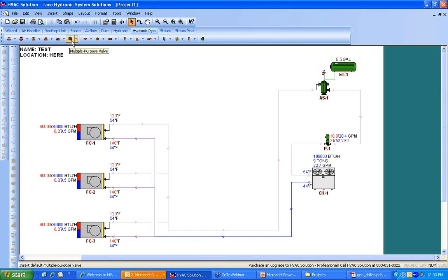You can put as much detail as you want into this drawing, depending on what stage the project is and who you're making the drawing for. You can put strainers in, you can put joints, expansion joints, relief valves, temperature gauges. If I want to put a temperature gauge on here so I know the water temperature coming to and from the chiller, I can do that. It's a little spot I don't like it there though. All right, we'll just leave it there for now.